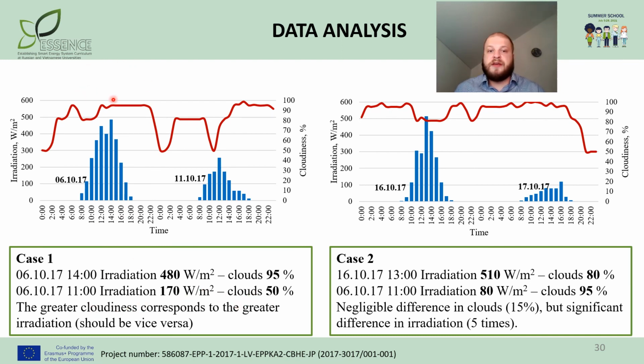And we may have errors associated with data contradictions, because sometimes the greater cloudiness may correspond to the greater irradiation, and the lower cloudiness may correspond to the lower irradiation, which is actually impossible from the physical point of view. And for this reason, data analysis, data preprocessing, and selecting relevant data sources are of crucial importance for energy management systems and for solving each specific task within the framework of implementing this energy management system in practice.